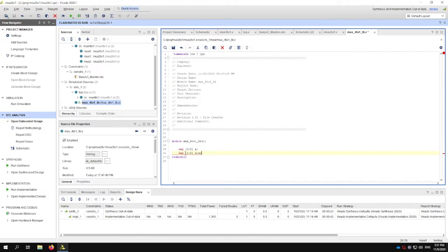And finally, the only other signal in my MUX 4:1 declaration was the output Y. All my inputs are declared as type reg. That's the general rule, because I'm going to vary them. I'm going to change their values, but only every, let's say, 100 or 500 nanoseconds. My outputs are just going to be declared as a wire, my output Y.